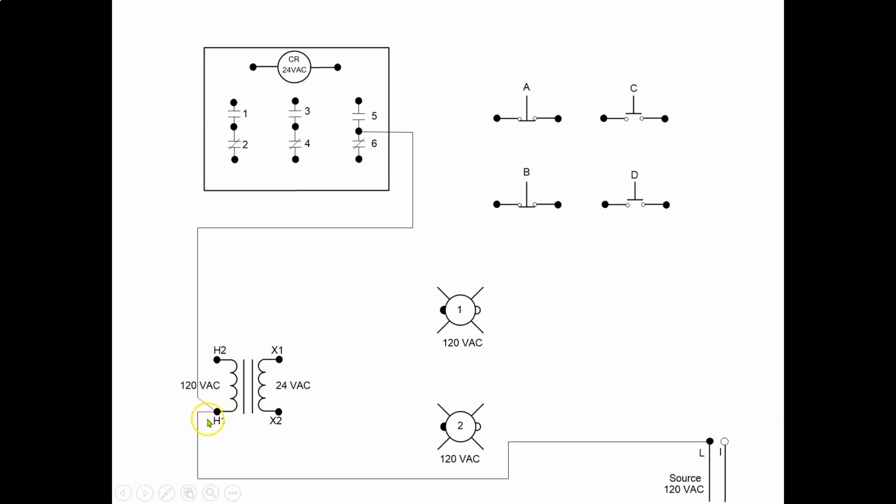What you would do instead, you would bring from your source, line 1, to the high side of your transformer, and then you would just stack another lead on top of that and branch off in parallel instead of cutting those conductors and splicing them together. You did this in first year. You didn't cut your conductors and splice them together, you actually stacked the conductors. So we have to come in with 90-degree angles and 45s out. So in with 90, 45s out.